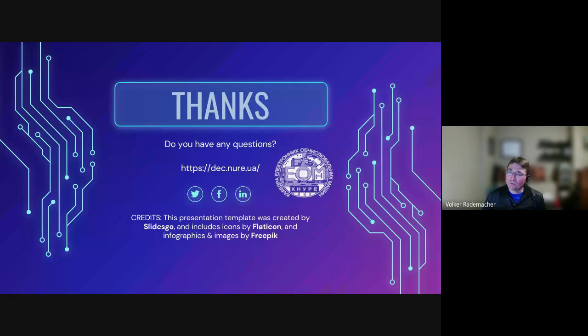I don't know if you know a BGA, ball grid array. It means the connections for the chip package are underneath the chip. And you cannot access it easily with multimeters, with oscilloscopes. You have to make test points. So it is more difficult to prototype.